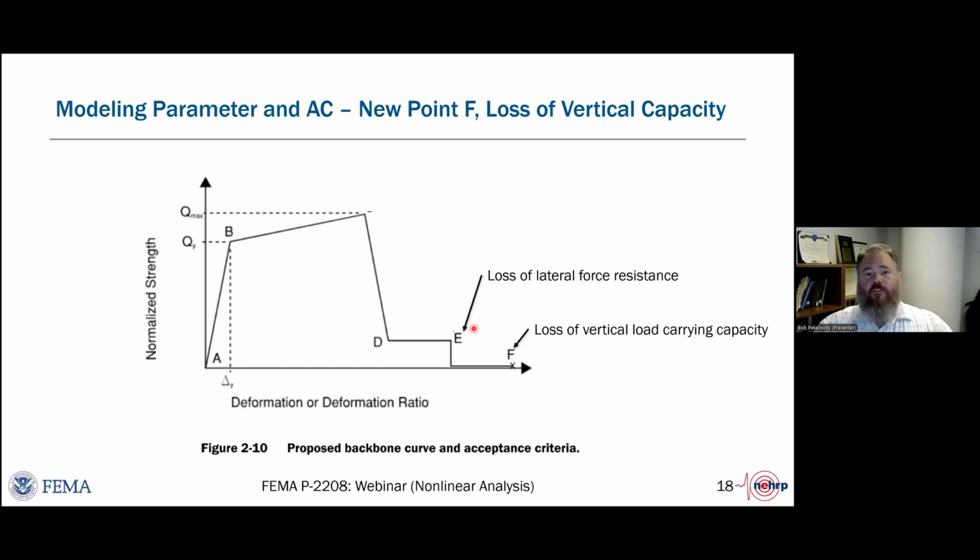And what is just as essential is being able to separate buildings that are just not as good as a new building from buildings that are truly dangerous. And so if every building fails the standard, then it's hard to really separate just not good from dangerous. And so one way to do that is to have more accurate models, or at least models that are closer to predicting collapse than the previous models do.